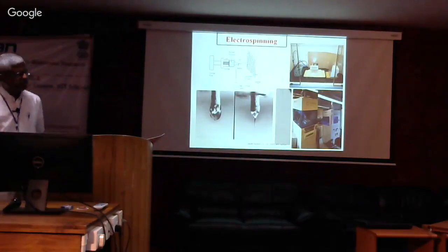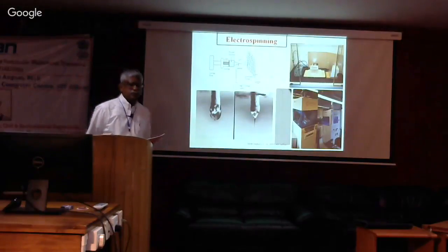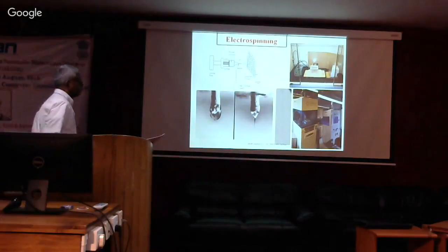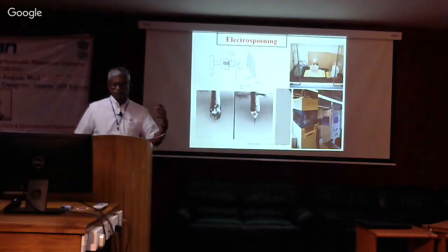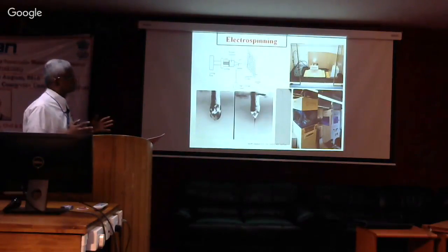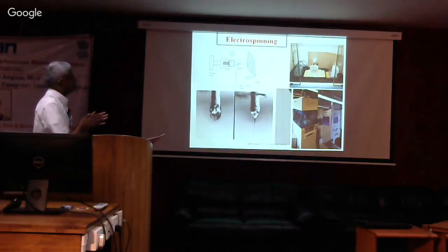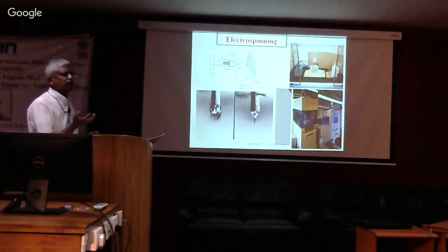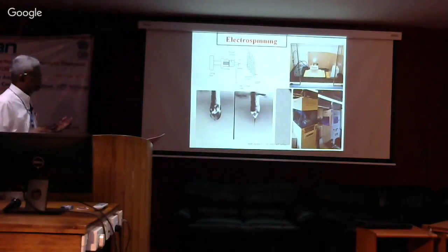If you run a unit like this for a few hours, let's say 3 to 4 hours is the most common, it depends on the polymer solvent mixture. Typically with polyacrylonitrile, in 3 to 4 hours we would get only maybe 5 grams, 10 grams of this material. It's a very slow process, so of course that process has to be expedited.